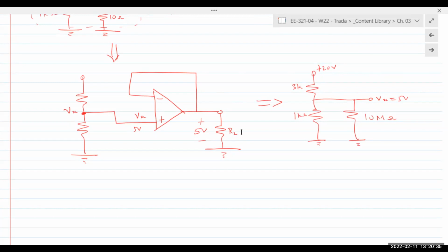Obviously, when we are designing a circuit, we would take a look at what that input impedance is, calculate the voltage from here, and calculate the exact voltage that is needed. There's lots of other things that go into the operation. We could also have a Zener diode in there to keep the output at 5 volts. We might actually have 6 volts coming out to account for fluctuations and add a Zener diode right there. So it just depends on what kind of circuit you want and what kind of adapter you want to build.